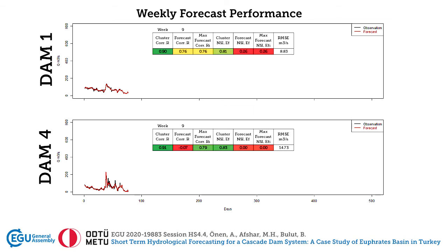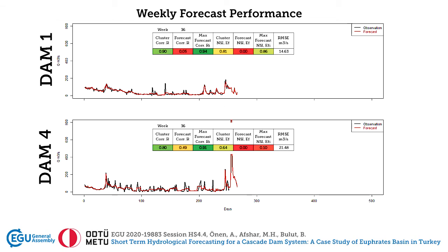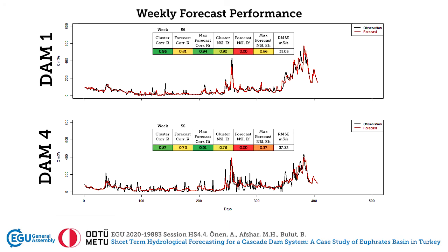As you can see, while we obtain high correlation between our datasets, our Nash-Sutcliffe values remain low. As we inspected, the main reason for these statistics is temporal mismatch. As I said earlier, we are still trying to develop a proper temporal correction for our system. For this, we have to wait because we need facility data to accumulate to create a better understanding of the cascade link in our model. We only have 2 years of data since the facilities are relatively new to operation.